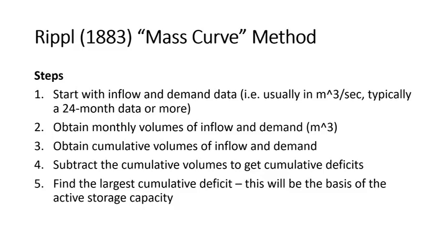Now from there, we obtain the monthly volumes of inflow and demand, so we convert from cubic meters per second to cubic meters per month. And then the next step is to obtain the cumulative volumes of inflow and demand.